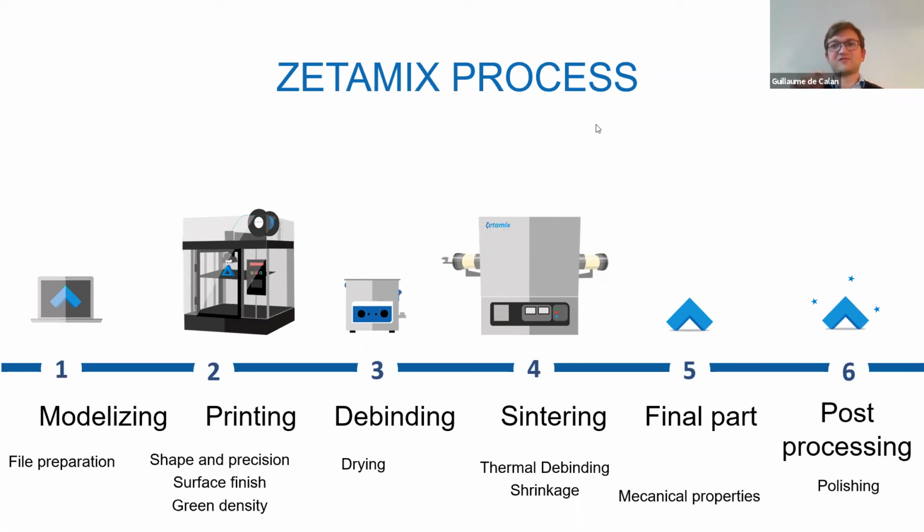You have a first part of the cycle where you burn the binder, which we call the thermal debinding, and then the second part of the cycle where you sinter the part. So that's where you get it dense. But all this is done in the same furnace. So practically speaking, there's mainly 2 steps: debinding, sintering.